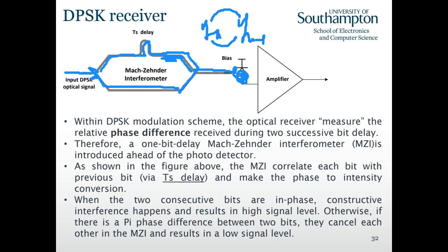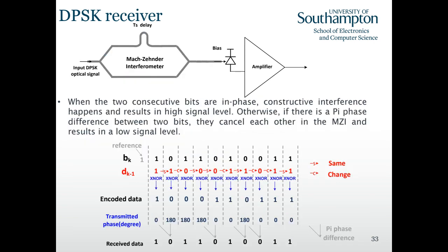So finally, if we look at the example again, let's go through this step by step. As a transmitter, the first transmitted symbol is 1, and then we have the incoming bit 1. So the next transmission will be 1. It's delayed to be the reference of the next transmission. Incoming bit is 0. We need to change the next transmission from 1 to 0.